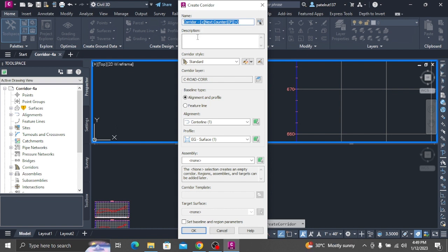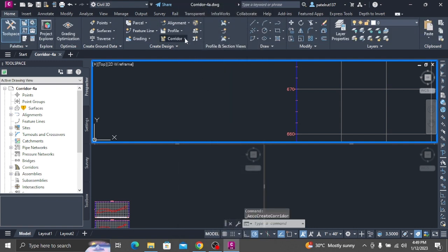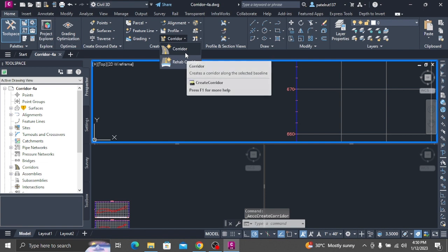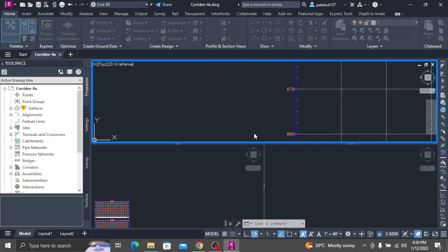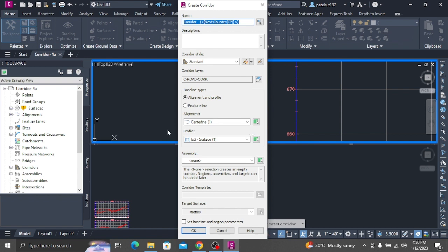The elevations and offsets are displayed on the grid axis. The cross-section view contains the assembly, as well as the other adjacent objects. At the current station, the offset alignments are represented by vertical green lines, and the existing ground surface is represented by the horizontal red line. The vertical red line in the center of the grid represents the assembly baseline. Profile intersections with the baseline are indicated by markers.